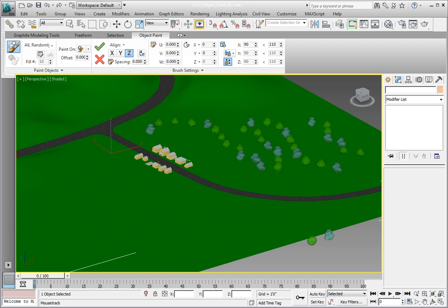with each other. In the Brush Settings panel, Scatter section, set the value for the U scatter amount to 400 and then press Enter. You'll see that the trees no longer run directly along the path, but are offset to either side, giving a slightly more random look to the placement of the trees.